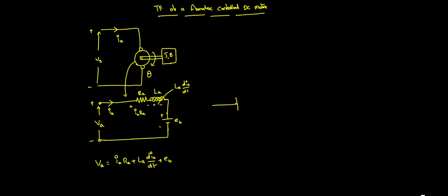This system has a certain amount of mass and possesses an inertia J. The twisting moment of force is called the torque, and the angular displacement is theta. There is also a frictional coefficient, which we assume is B. So what is the equation we will write?